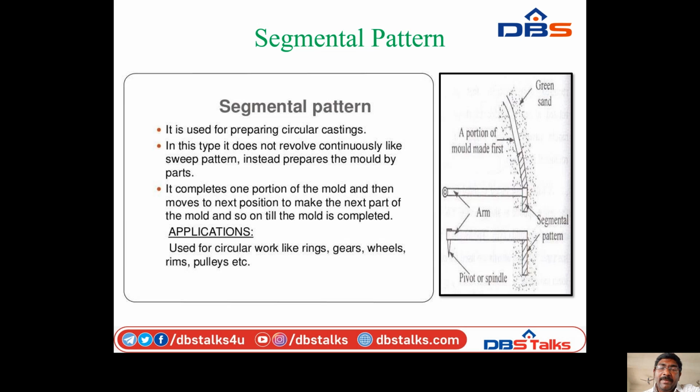Next, segmental pattern. A segmental pattern resembles a sweep pattern in the sense that for getting the required shape, both use a part or portion of the pattern and not a full or compound pattern. Both segmental and sweep patterns generate circular shapes.